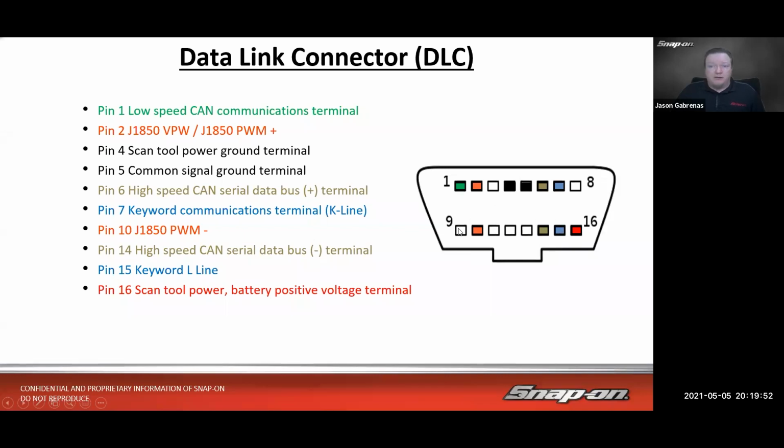Now we see all these other open channels there. That GM I was talking about, the global A network, those vehicles, they'll have their regular CAN, or I would say regular CAN, but their main bus on pin 6 and 14 as they need to. So engine, transmission, body control, that sort of thing. But then they'll also split out the chassis controls on these 2 pins. And then the object detection bus is on these 2 pins, right? So it terminates 3 CAN circuits at the DLC, plus all these other circuits there as well. So it can get pretty crowded on that connector. Sometimes we have to dig under the dash and find a sub connector where they connect together as well.